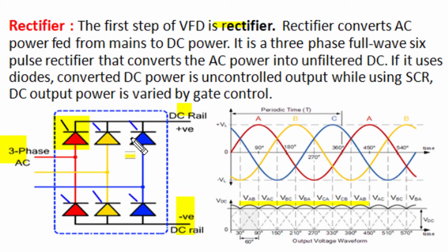Now these fully controlled rectifier circuits are basically bidirectional switching circuits, and they can convert the DC applied here into a three-phase AC because these thyristor switches can work in both directions. So when we have to use regenerative braking facilities in induction motors, we use such a fully controlled SCR type bridge rectifier. But in general applications, we will use a simple uncontrolled diode rectifier, which is not only economic in design, it is also convenient to operate and has more reliability and better performance.